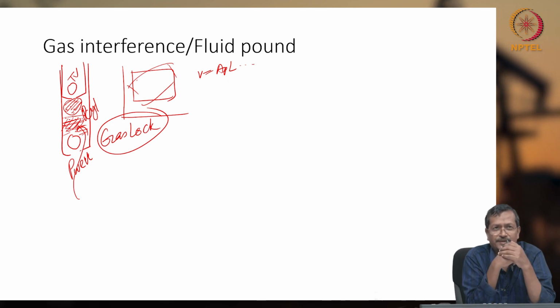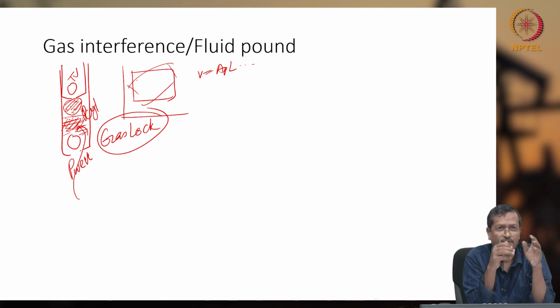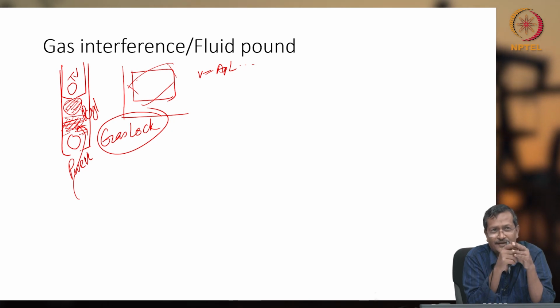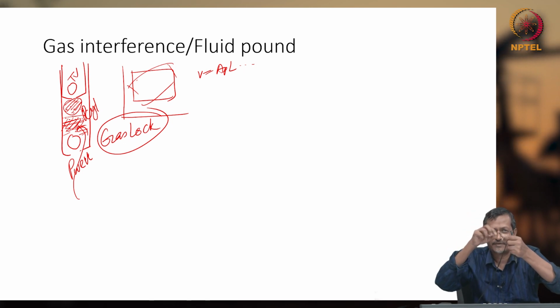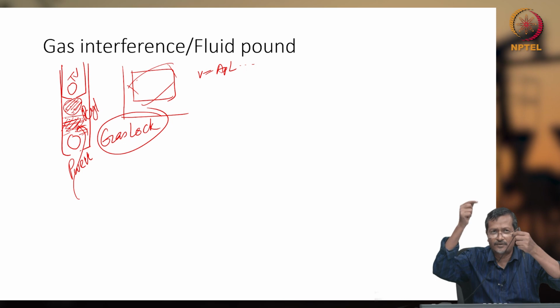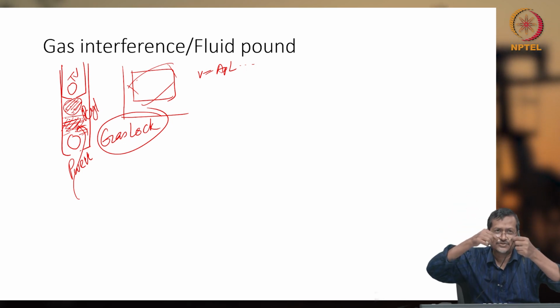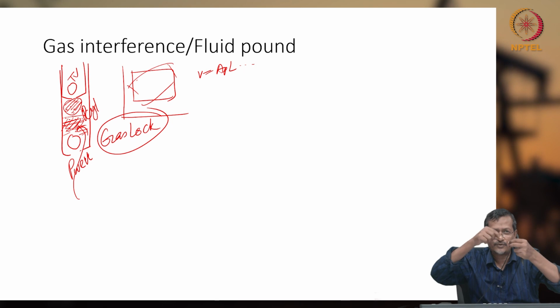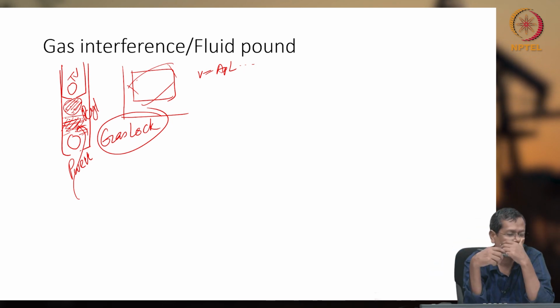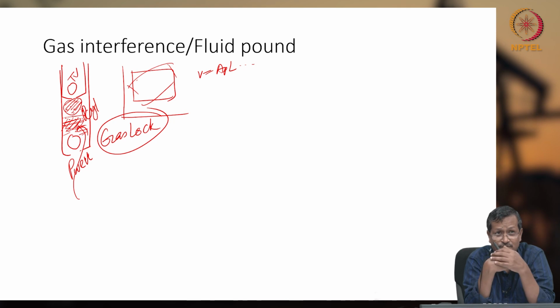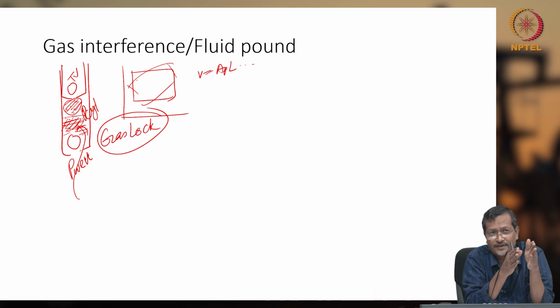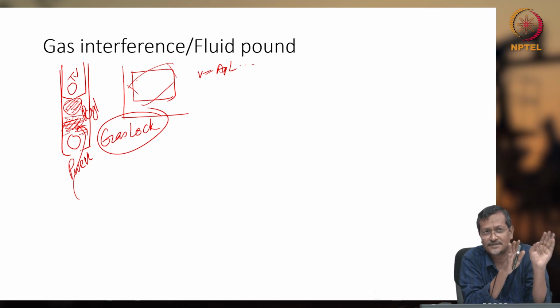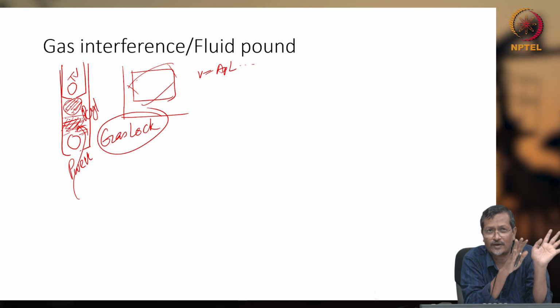I was discussing with some engineers, and they say if such a situation, gas lock, is there, you have to switch off the pump and allow leakage. Where is the leakage? Already we calculated leakage through the plunger and barrel, there will be some small gap. The traveling valve also might have some gap. You stop the pump and allow some leakage so that the cylinder cavity fills with liquid and gas can escape. That stoppage can be several days actually. Normally the production engineers will avoid gas lock by making certain mechanisms so that gas lock cannot appear. We will discuss later how to avoid it.